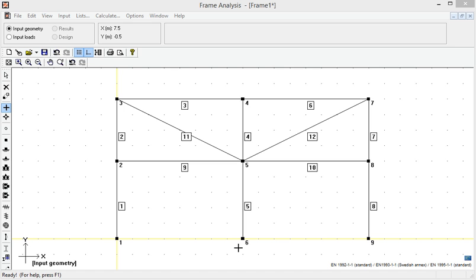The geometry is now defined, and each element is as default regarded as rigidly connected to the nodes. Each node, defined with a member tool, is also assumed to be braced with regard to out-of-plane instability. It is important to know when later a design is performed.